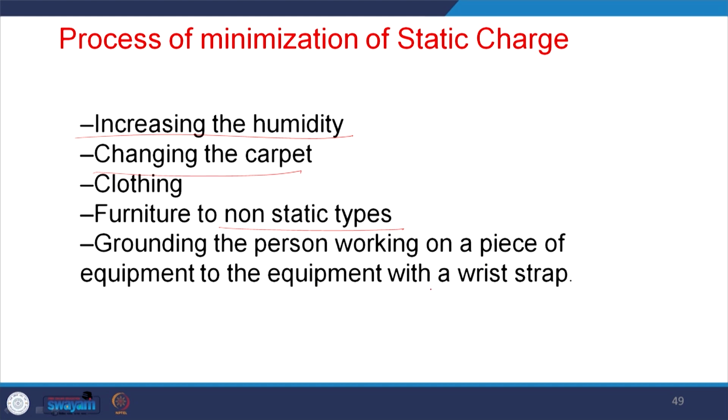Mostly it is used when technicians are soldering MOSFETs, because their hands may contain a sufficient amount of charge if they rub something, and once they touch the MOSFET, this charge will be trapped between the gate and source of the MOSFET, and thus it will automatically turn on. So, ultimately you get a MOSFET in a short circuit condition. For this reason, when they are soldering, they wear the wristband.